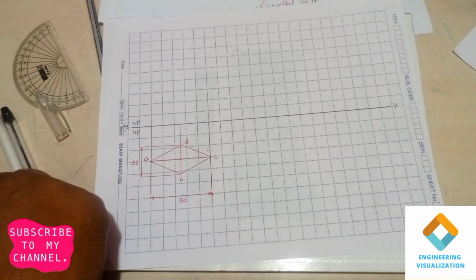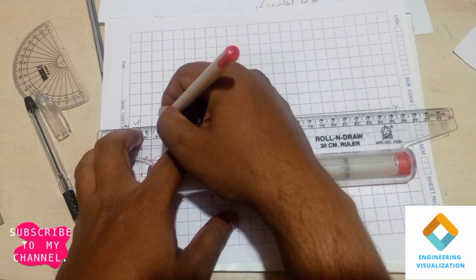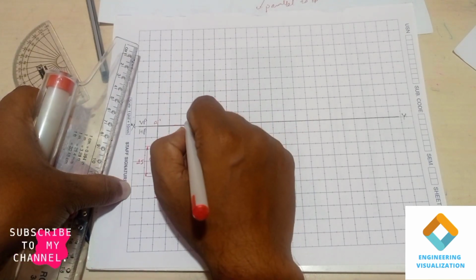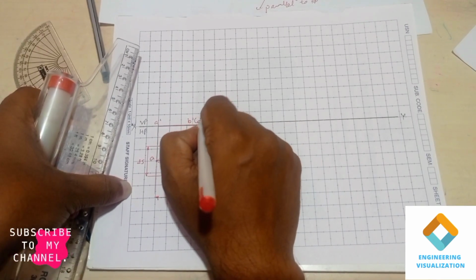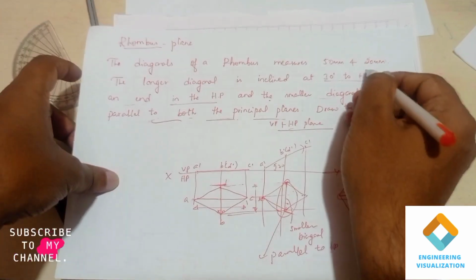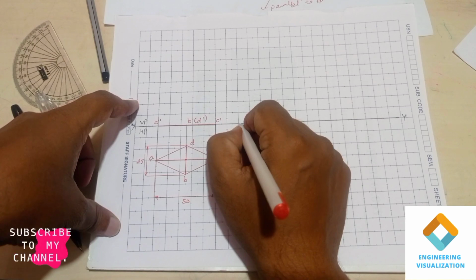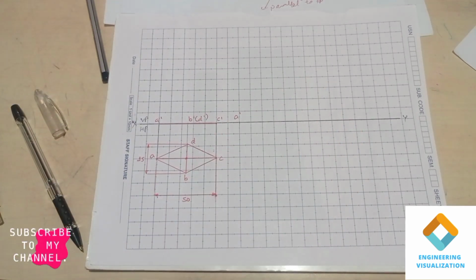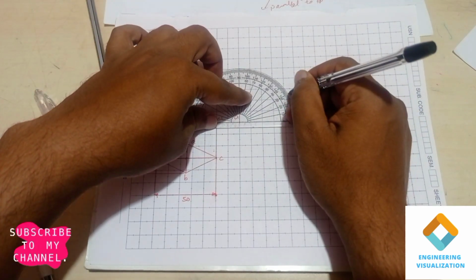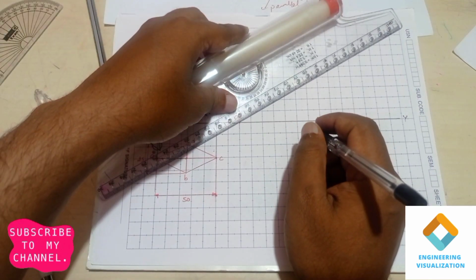Project it upward to construct the front view. A dash, B dash, and C dash, D dash are not visible from the front view. Now we have to take the inclination to HP, which is given as 30 degrees. First we mark one reference point A dash, take the protractor, mark an angle of 30 degrees, and draw an angle line passing through that point.